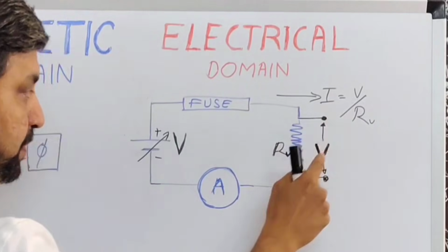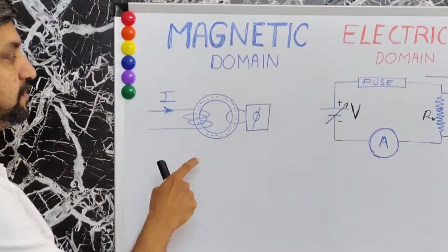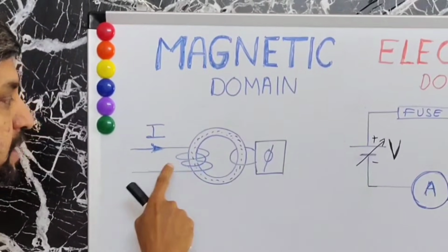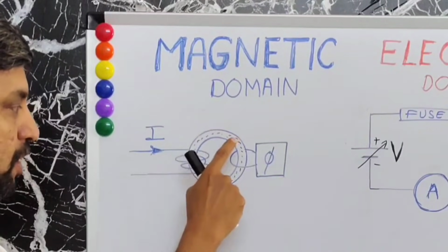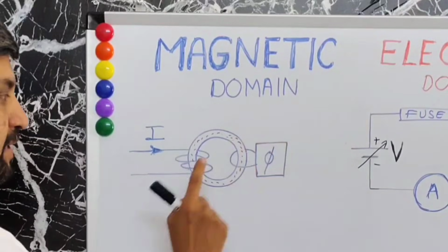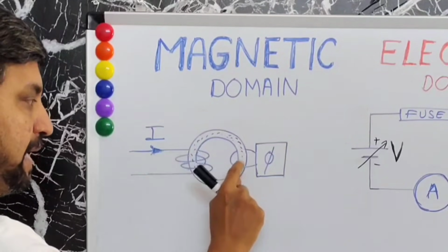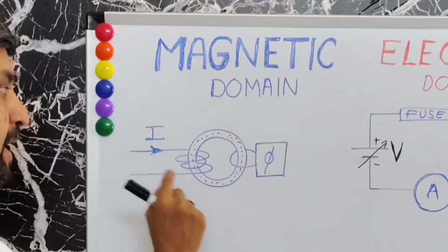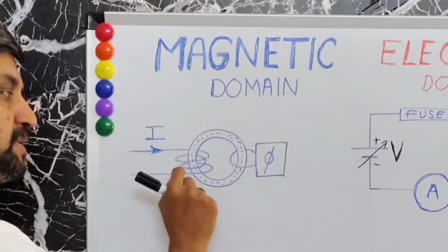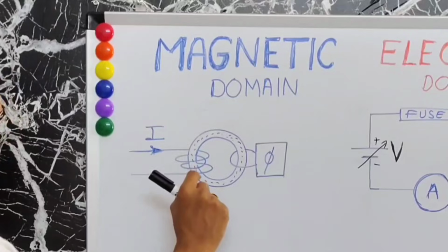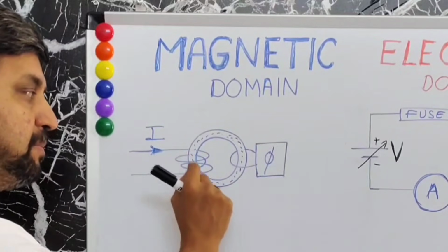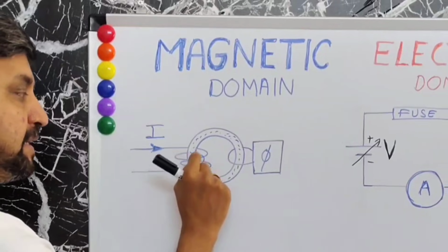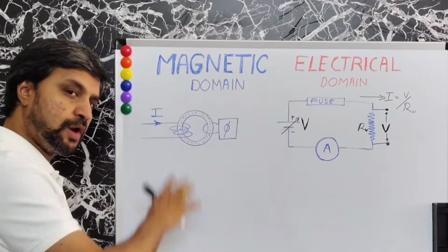and whatever applied voltage was coming across this resistor becomes zero. In the same way, in this magnetic circuit, when you apply a magnetomotive force, the resultant flux gets formed. Like the fuse in that circuitry, this core has a maximum amount of flux that it can handle. If you keep increasing this magnetomotive force, the flux reaches its maximum level, and you'll find that the whole effect of this inductance and the magnetic system collapses.